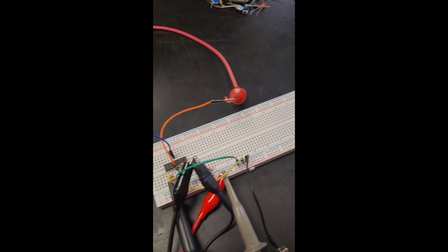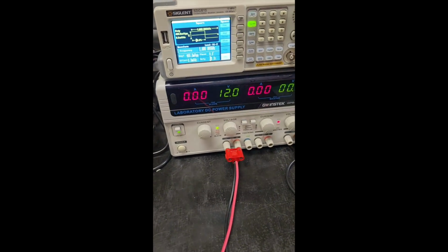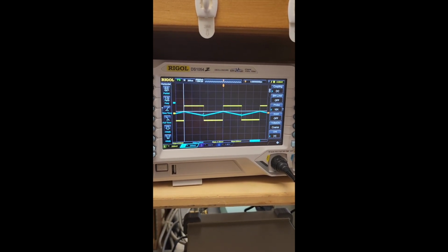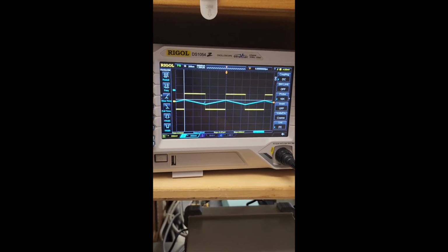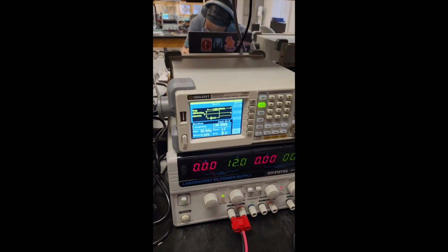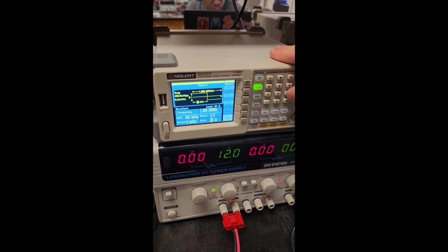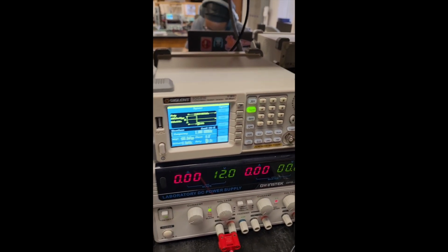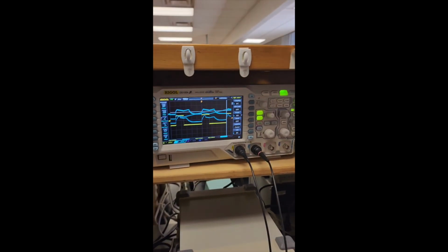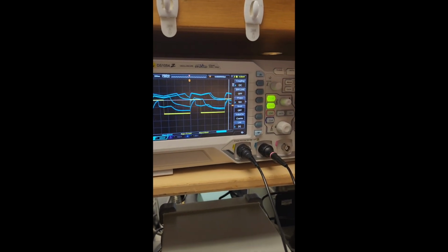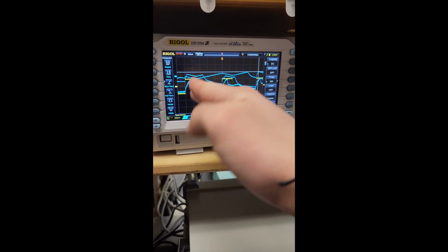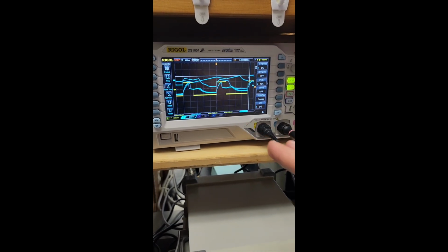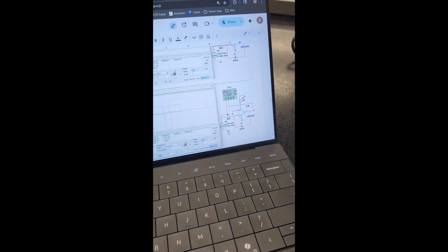As seen here, we have set up our circuit again, and with the same settings and at 50%, we can still observe our same waveform, this time zoomed in a little bit more. And as we change our duty cycle to say 30%, we can see it messes up the waveform quite a bit. However, if we pause for a second, we can kind of observe this sloping that we can see.